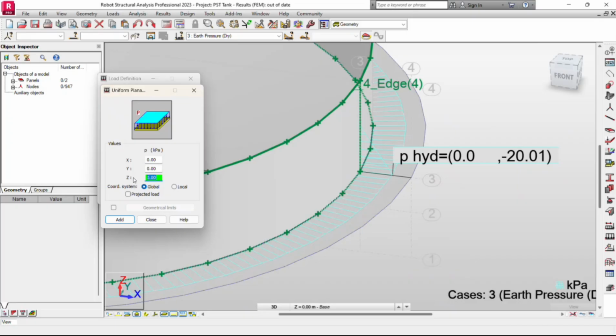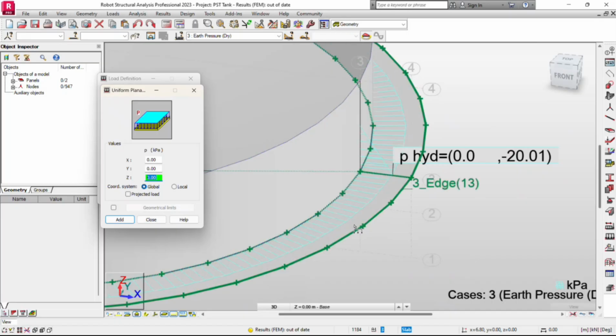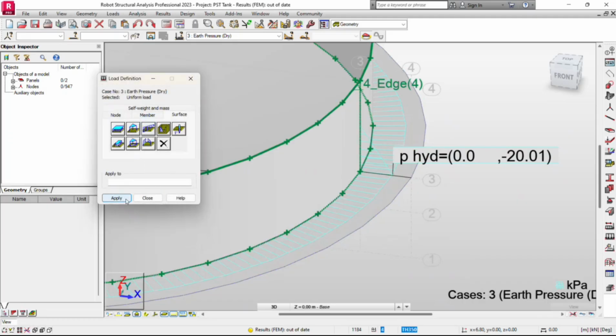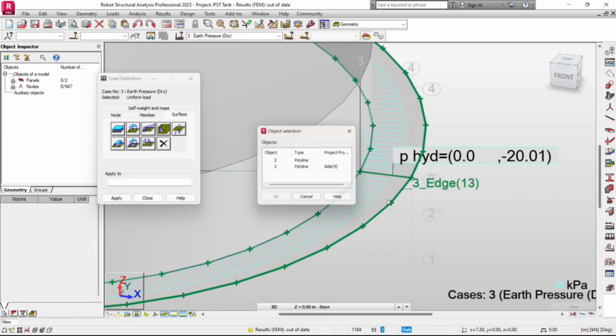And then you specify here the pressure. So the question now is, what's the pressure that we are going to apply in here? Of course, you've got the unit weight 20 kilonewton per cubic meter multiplied by a height of 1 meter. So that's 20 kilopascals. I hope that's pretty much straightforward without showing you the calculation. All right. And take note that you always need to apply negative here. It denotes a sign of downward.